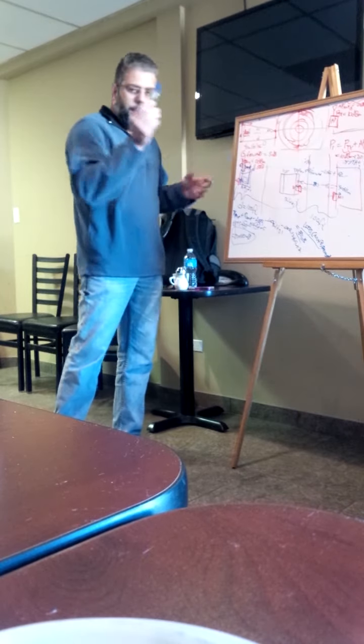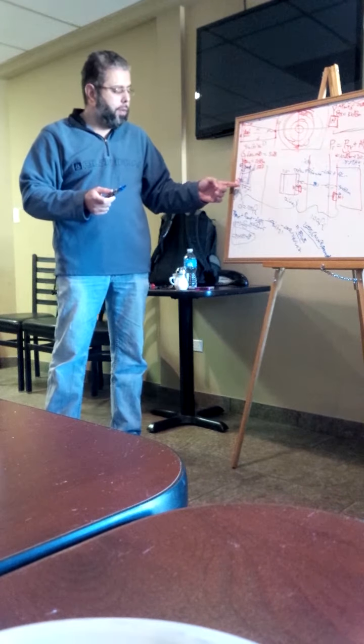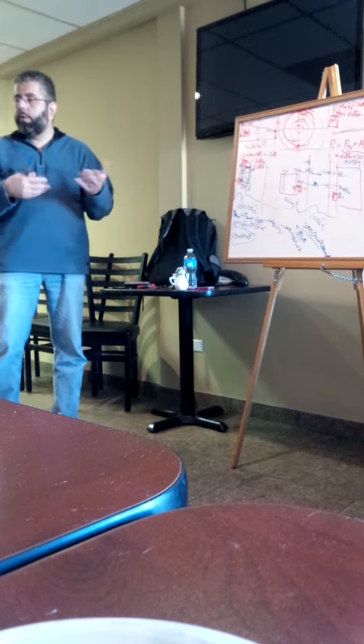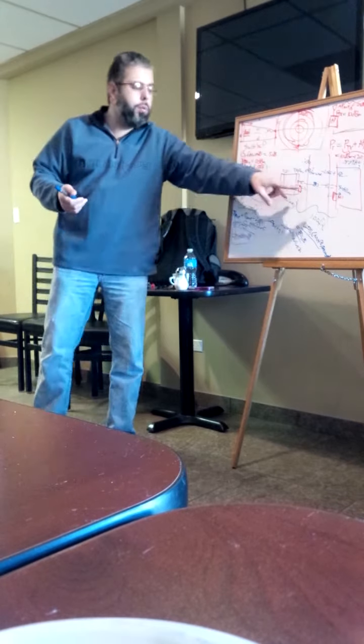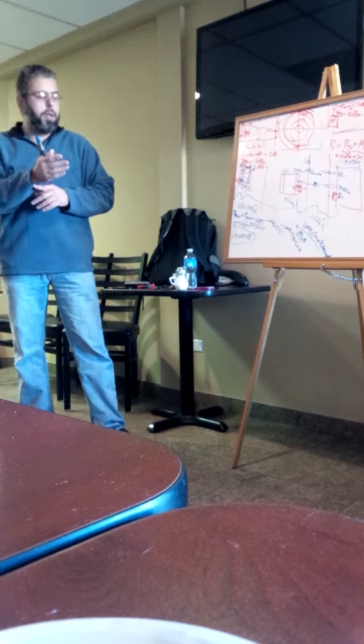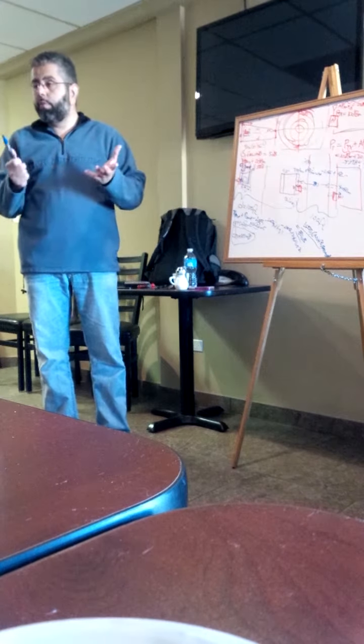It was just kind of something else, or it was at the edge of the building and it could see around the building, then you might not get the whole loss in here. That's why I'm saying it'll be somewhere between 0 and 40 dB of delta, probably between two equidistant buildings, where one is a direct line of sight and the other one is going through two buildings in order to get to the guy. So that might be 40 dB of delta.